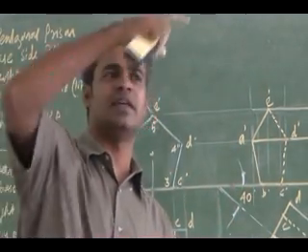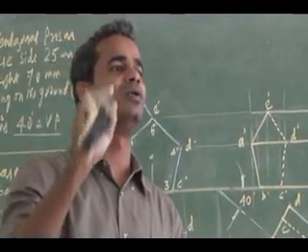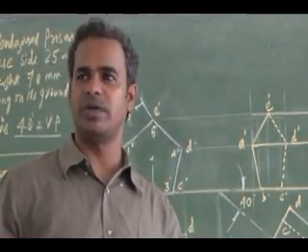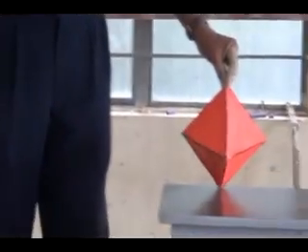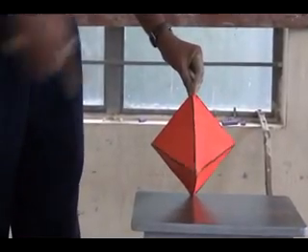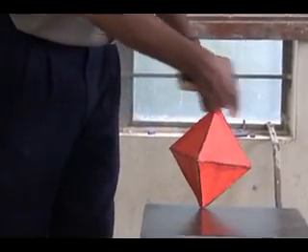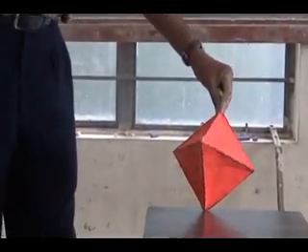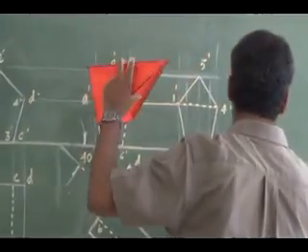From that corner, while constructing the square, one of the sides should be 20-degree inclined to HP. See here, this is the inclined orientation. I will be tilting it, assuming the axis inclination is perpendicular to VP, and a corner is resting on HP, and an adjacent side is 20-degree inclined to HP. This way I have to draw the true shape.